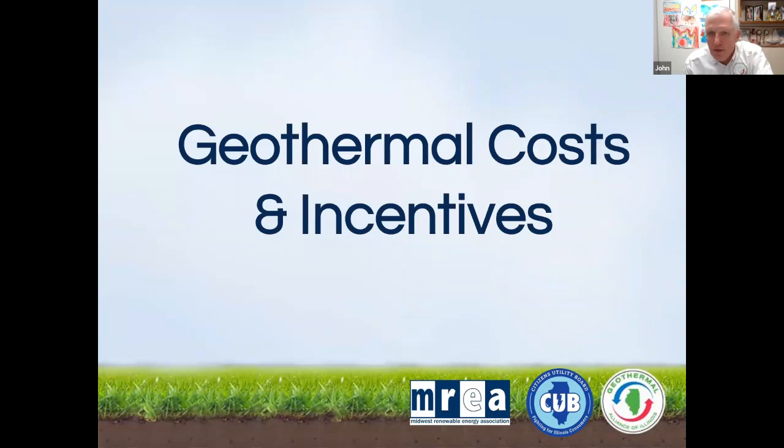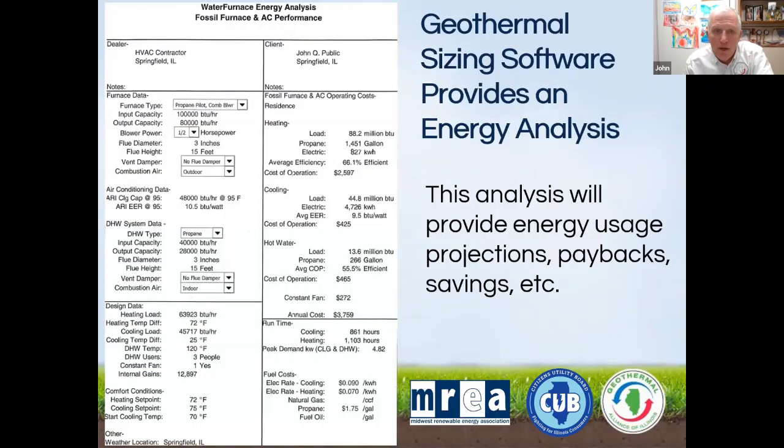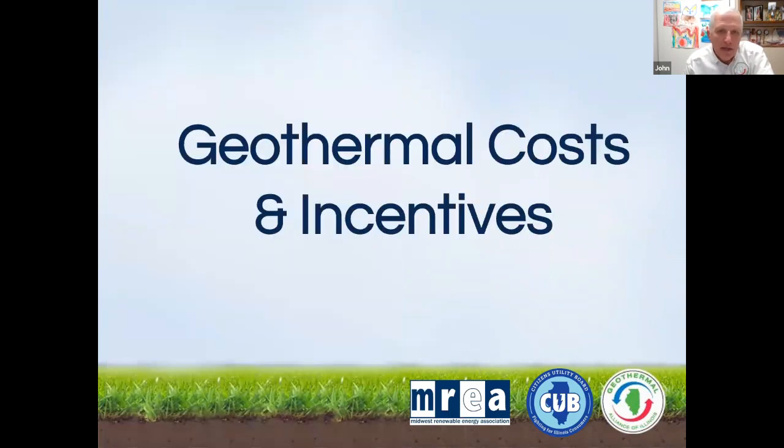And it's really important because if you don't have the system sized the right way, if you oversize a system, well, it'll cost a lot more for installation, number one, and you won't get proper dehumidification in the summer, number two. And if you undersize the system, you're going to get to heating season in the winter, and most people with an undersized system aren't going to be very happy because they're either going to be very cold or they're going to pay a lot for backup heat to meet the heating and cooling requirements. So you want a system that's designed the right way and sized the right way.